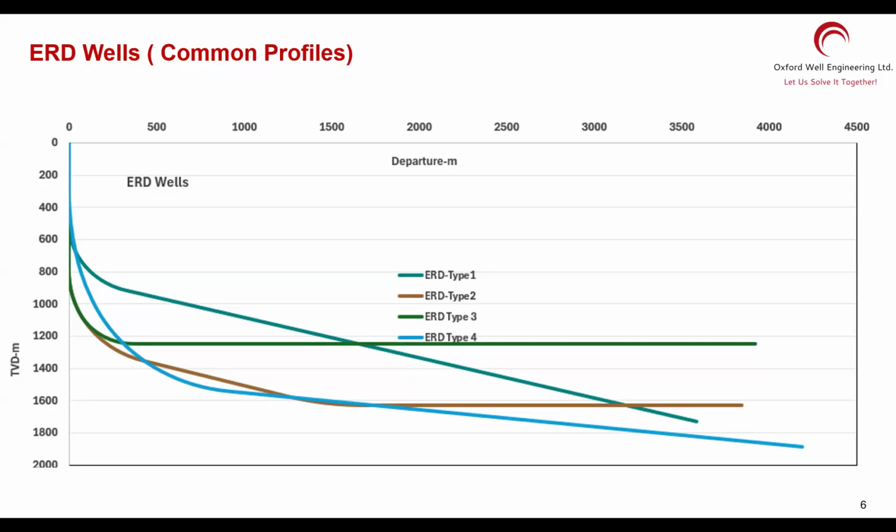For example, in a shallow horizontal well, how are you going to push the BHA into the horizontal well? Suppose you are drilling the last section, you cannot even push it down from the top. A lot of the time it is so bad because of the drag you have in the system. Are you going to overcome that drag somehow? There are technologies for it. Okay, a long list of technologies. So let's keep moving.